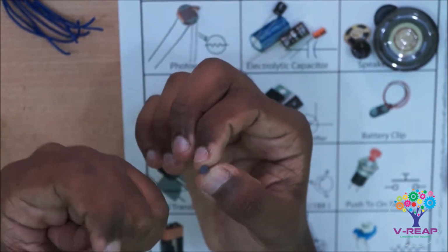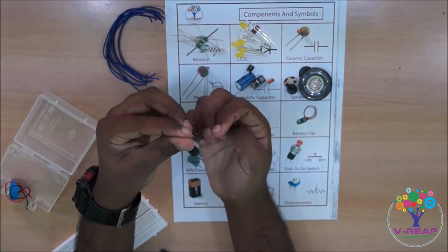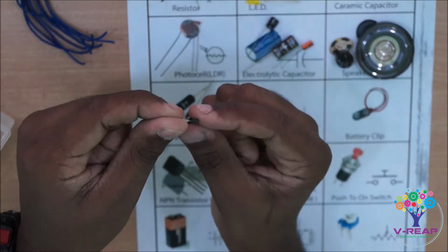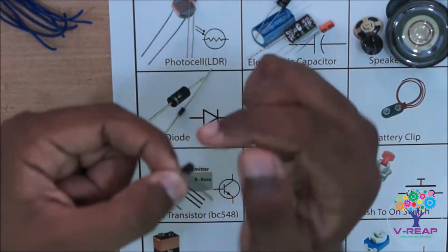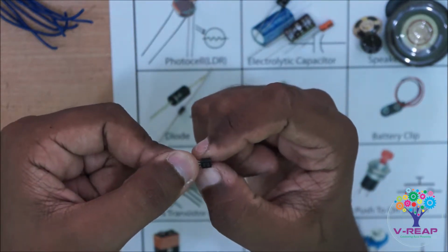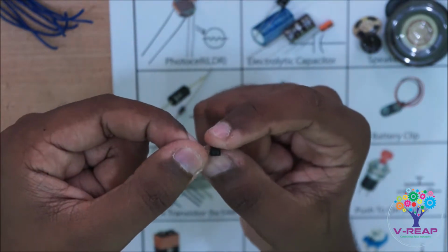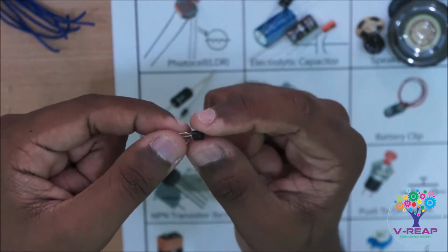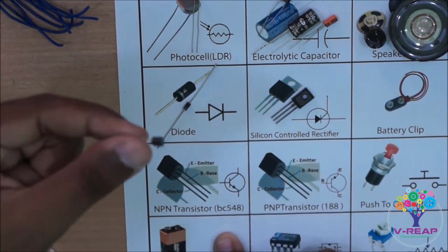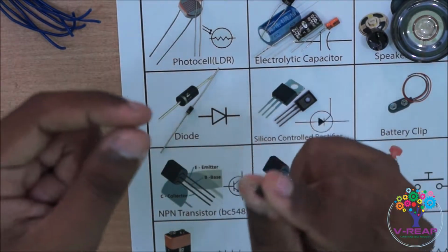There are two types of transistors, NPN and PNP. You can identify these transistors based on the three terminals that are present on it and the engraving on the casing that is present. If you look closely on the case, you can find small printing on it giving the transistor code. As you can see, the transistor with the code BC548 on it is an NPN transistor, which is this.